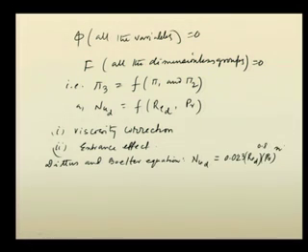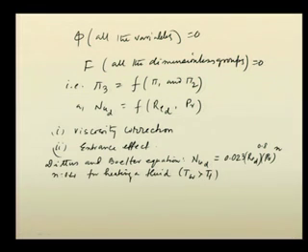Here n is given as 0.4 for heating a fluid, that means wall temperature Tw is greater than fluid temperature Tf, and n is equal to 0.3 for cooling a fluid, when Tw is less than Tf. That means the surface temperature is less than the fluid temperature, so you are cooling the fluid.